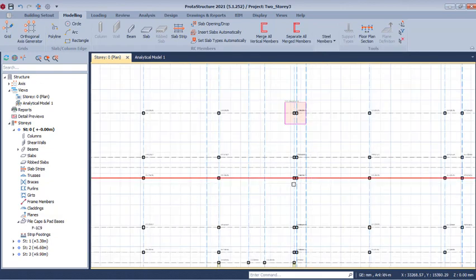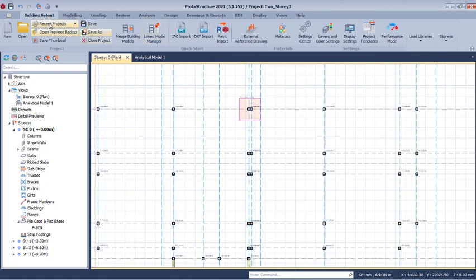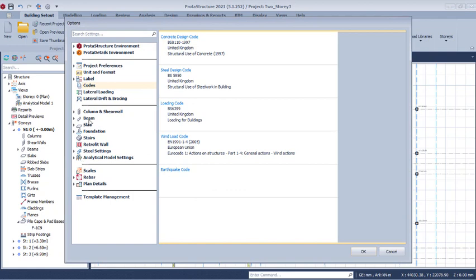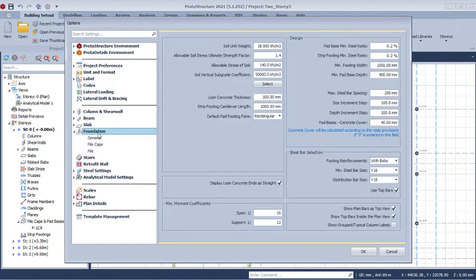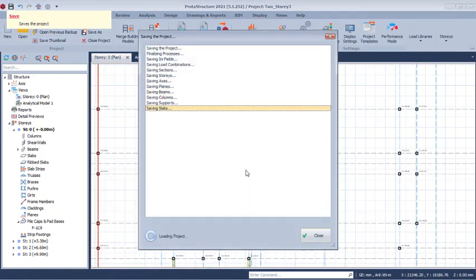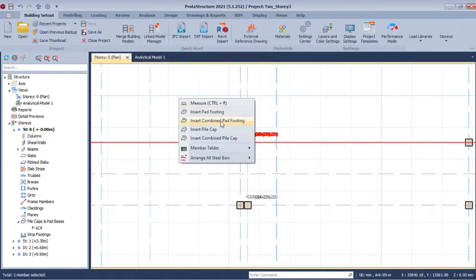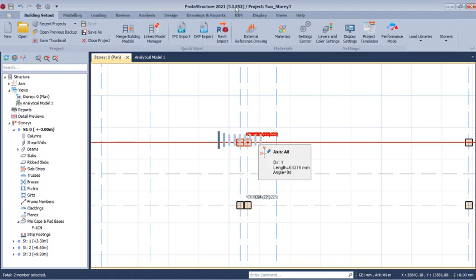The same thing is applicable to this. For us not to observe that top and bottom reinforcement, there's a setting we need to go and change, which we are going to be doing right away. We have to navigate to the building set out, and then you come to the setting center. In this setting center dialog, you have to navigate to where our foundations are. So come to these foundations, general right there. In this general, uncheck this, this, and this. This is just what we need to uncheck. Click on the OK option, and then now save the project. Let's try it and see if we have a double footing right there. Select the two columns and then use combine footings. Mind you, this is ProtaStructure 2021 I'm using for the design.